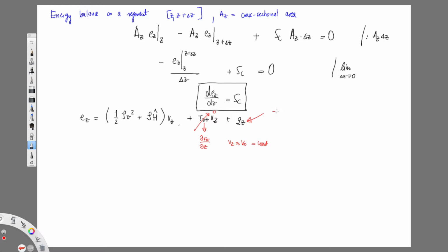This is going to be K effective in the Z direction, so ZZ direction, if you will. That's how it's typically denoted. So this is the effective thermal conductivity for the sphere pack plus fluid.